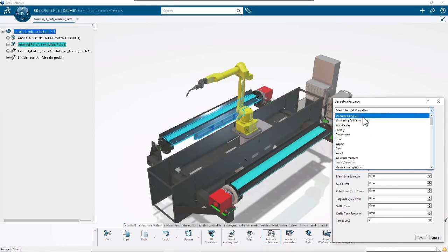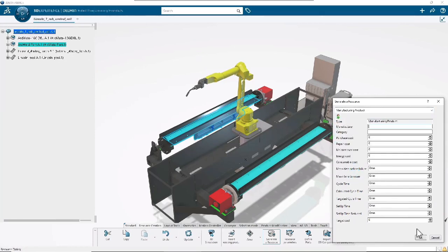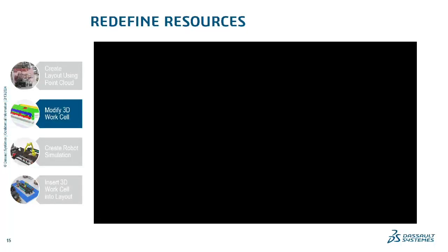Once you commit this command, you can't undo it. So once you've defined something as a tool, it's defined as a tool. I always save right before I do this because I've more than once clicked on the wrong thing and hit OK and not realized I did it, and you can't Control Z out of it. So I save, I do it, and then I save again, assuming I didn't mess up and have to close and reopen.